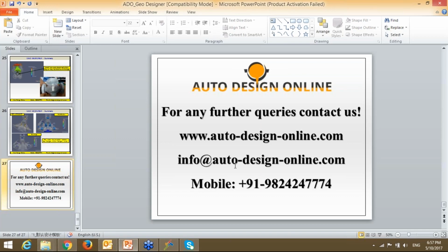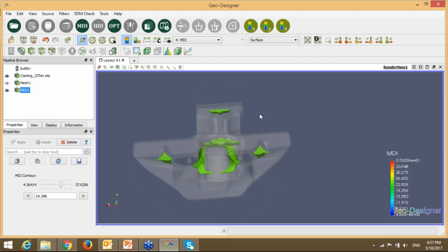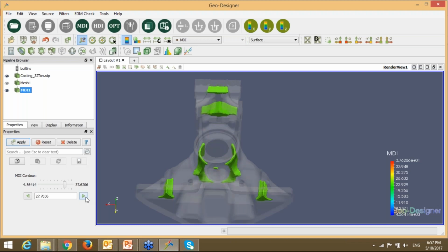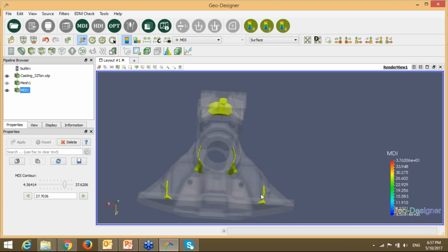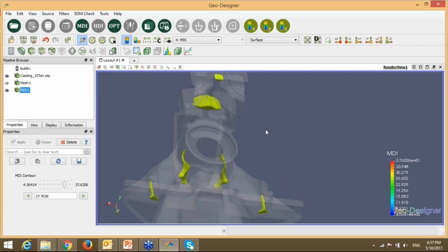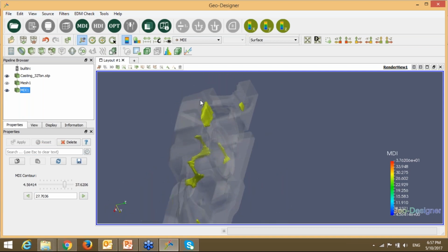One more question that is coming is whether it takes care of sleeve types like exothermic sleeve or HDS. Yes, it takes care. How it takes care is that the areas which show very little mass will work with a low density sleeve, but the areas showing higher mass will require a costly or high exothermic sleeve with high density to address them.